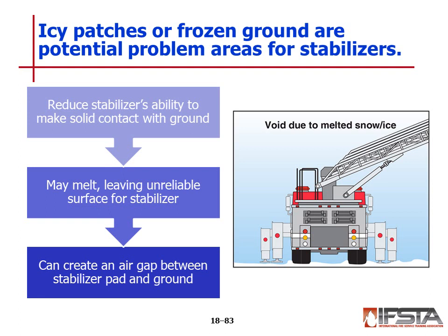One effect of ice melting is the creation of an air gap between the stabilizer pad and the ground, compromising stability of the apparatus. The driver operator must constantly monitor the stabilizers and be prepared to lower them further for maximum contact with the ground.